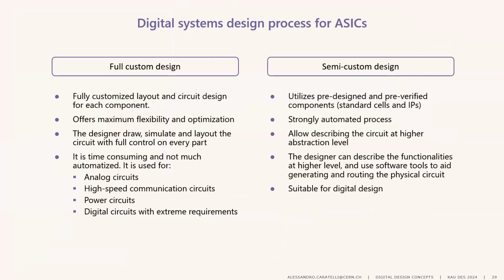So before actually entering this, one more concept that is probably worth mentioning is the difference between full custom design and what we call semi-custom design. Full custom design is when basically the designer has full control to customize the layout of the circuit for each component. He can draw basically everything. This offers the maximum flexibility because you're actually drawing how the transistor is done, basically. But of course, this is time consuming, as it is not a very automatized process.